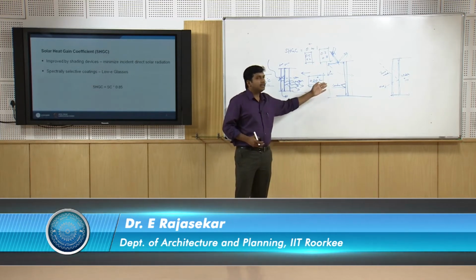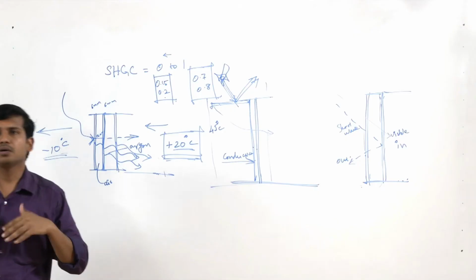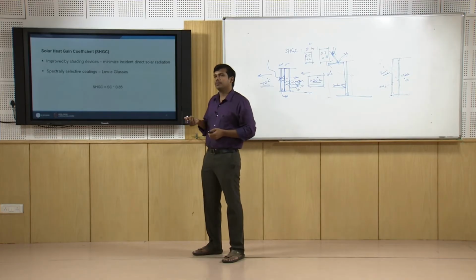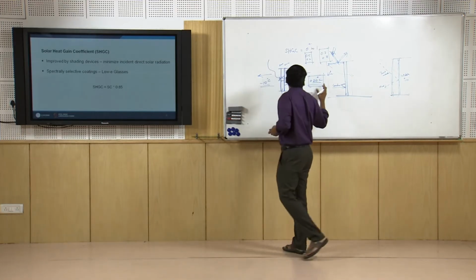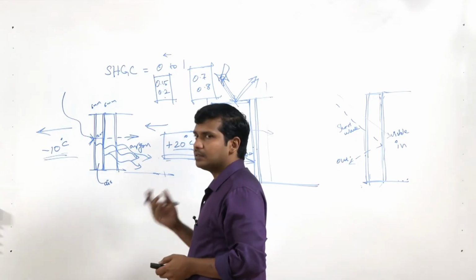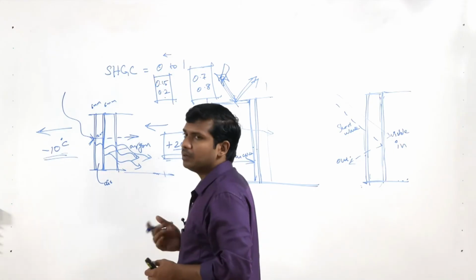system are highly radiative, they have a lot of radiant heat gain, they started using a coated glass or a tinted glass. Essentially it is a mix of bronze or some kind of metal which is mixed in the glass, so the glass gets darker. As a consequence, the light transmittance through the glass came down drastically.